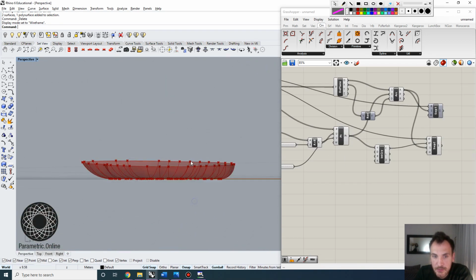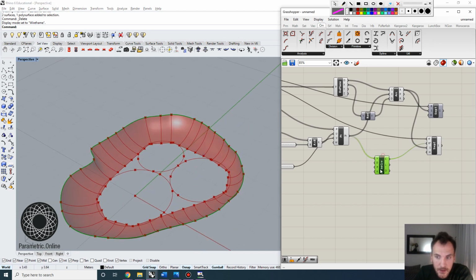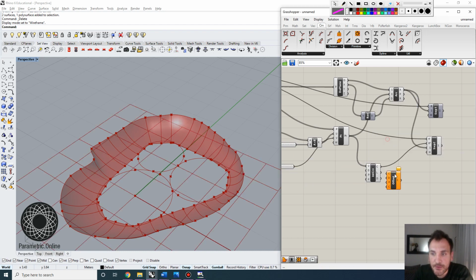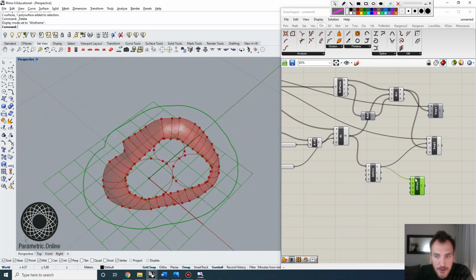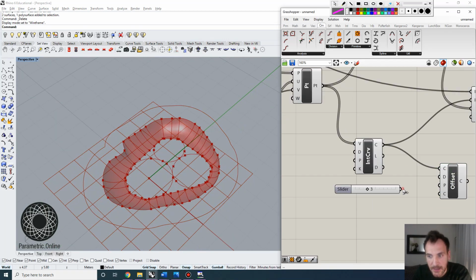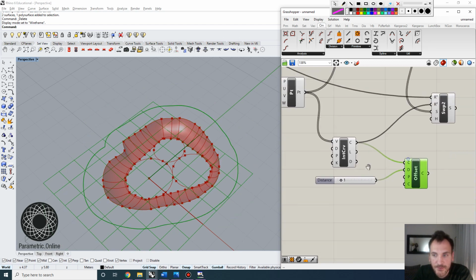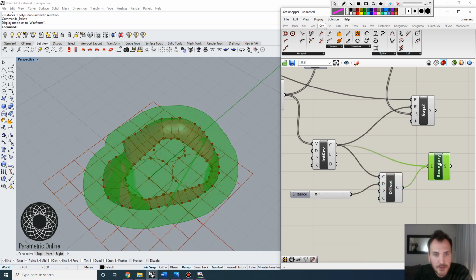But one option that we have, once all these points are coplanar, is that you can also offset this one. If I offset this curve here, you can create an offset value that can act like a secondary base, right? So we can create some offset value, and then using these two, you can create a boundary condition. So you can combine these two. Let's see if this would work.